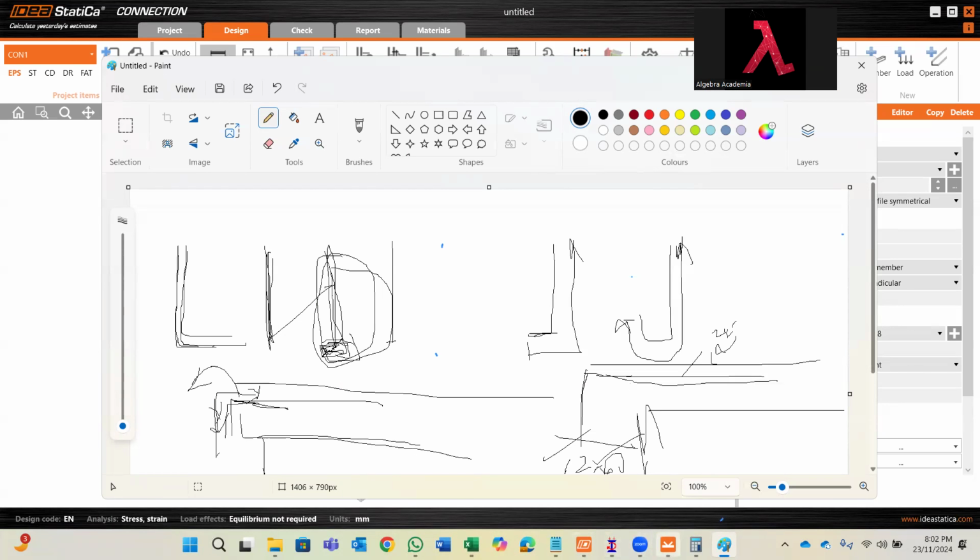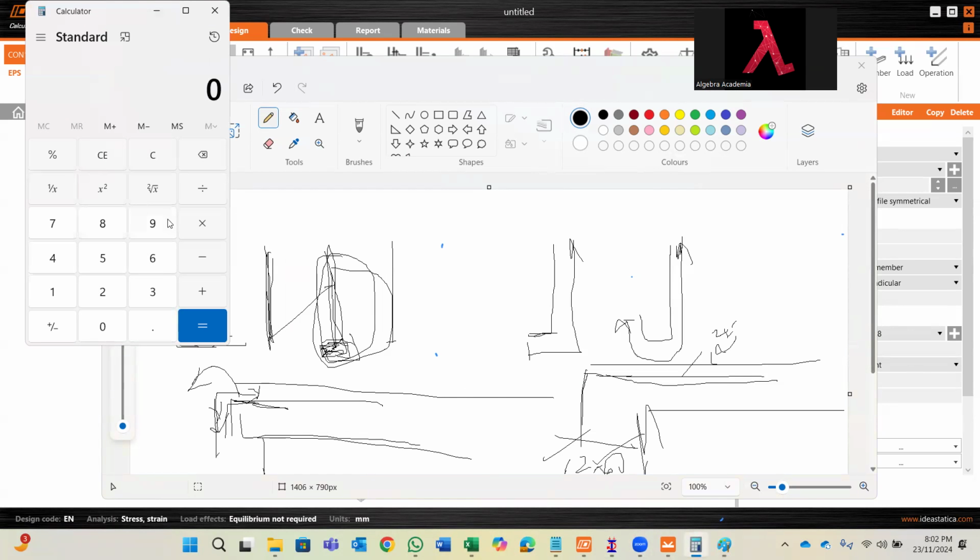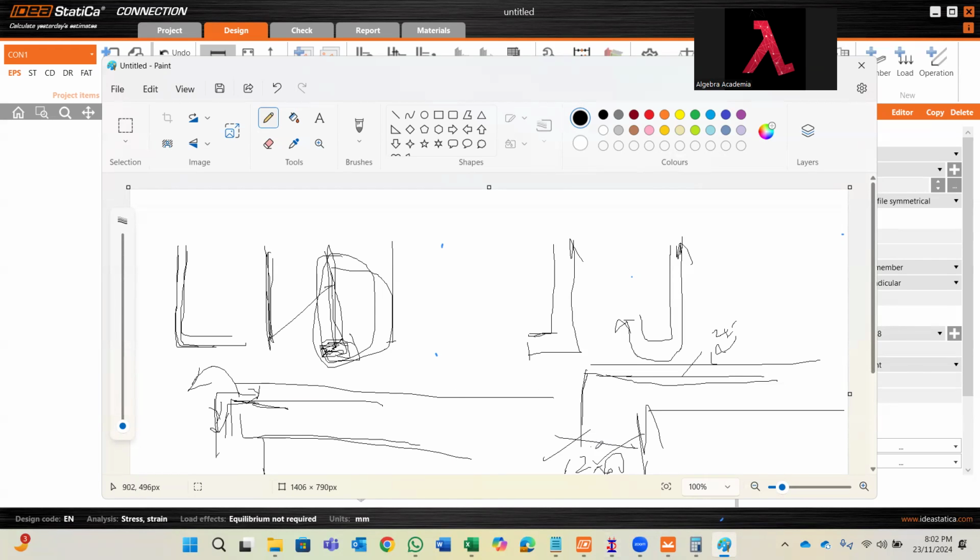So 50 times of 25 millimeter diameter is 1.25 meters, whereas your wall length is 2 meters. In that case I don't need to take it till the end and bend it. If I satisfy 50 times the diameter protruding inside the wall, that is more than enough. You're getting the point. This is what you need to understand here.